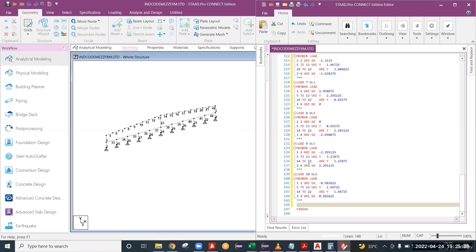Load combination, sir. Yes, because any structure, whether it is RCC or steel structure, we should not design it for primary load cases. That is the main thing I have told you in the previous classes. We should not design any structure for primary load cases, because all the loads will not act simultaneously at the same factor. Some may act higher than expected, some may act lower than expected. So based on that, our code has provided certain combinations here.